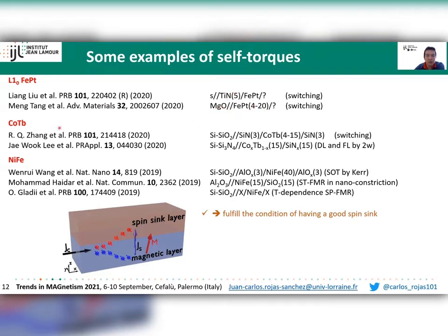Also in cobalt terbium, between two silicon nitride layers, that is very interesting, but I still don't understand everything that is driving this switching, because, as the authors report, there is no composition gradient. In our case, we tried like 5-6 years ago single cobalt terbium layers of different thicknesses, and we observed no switching in a single cobalt terbium layer. But of course, the materials here are different: directly on silicon oxide substrate, and the capping was aluminum oxide.